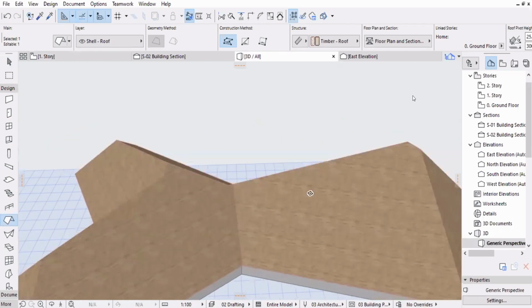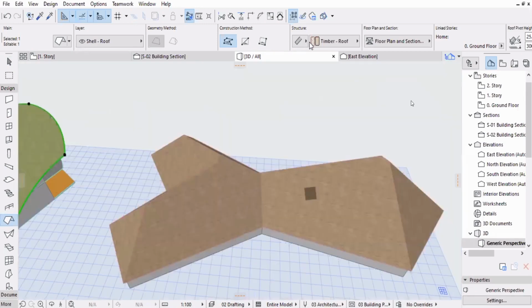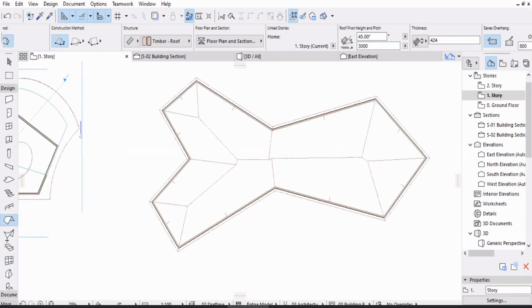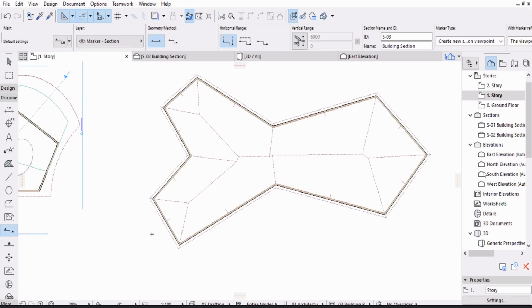And then you can actually select this holding shift and change its angle and change its thickness maybe. And then you can draw sections along this. Going to the documents section, hold my mouse here so that it draws the line.